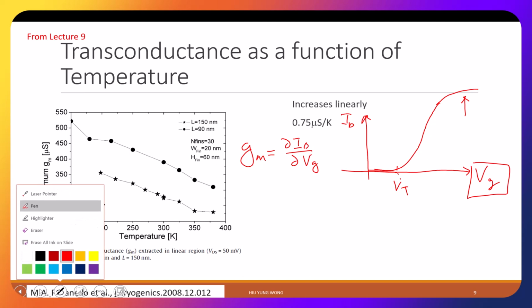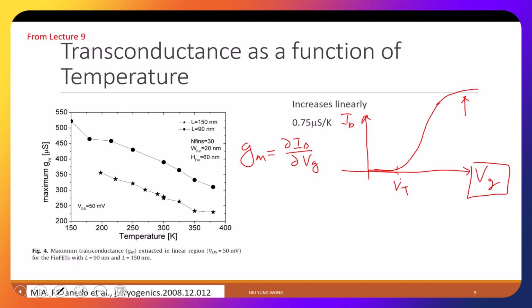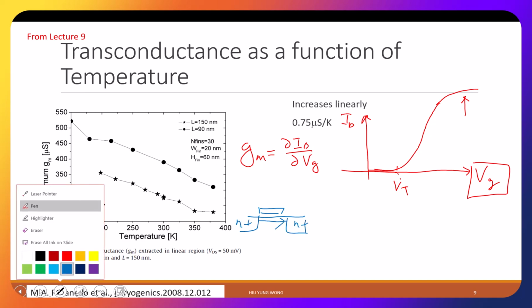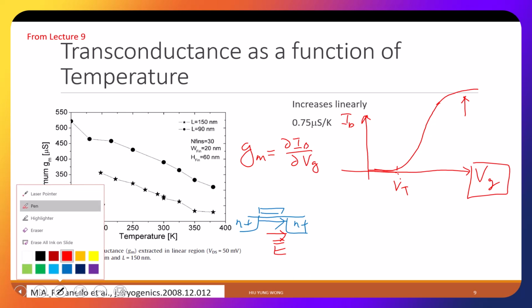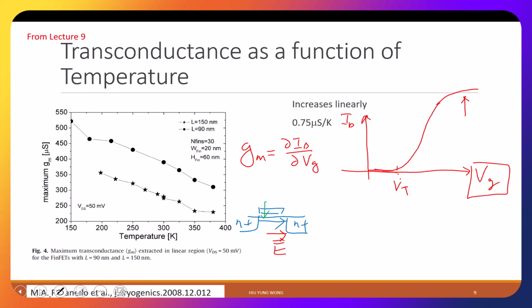That's why the discussion is useful. If you look at the transistor, you have N plus here, your current goes from here to here. You have velocity saturation only if your electric field is in the same direction as the transport. It's moving from left to right. When you increase VG, you only increase the electric field vertically to get more electrons and push them against the wall, right?